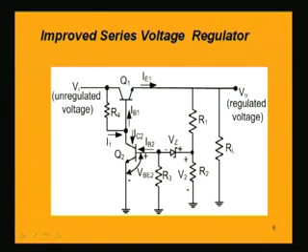So now if we apply again KVL in this loop, starting from here and ending at ground through this resistance R2, what we get? VBE2, that is the base to emitter voltage for the transistor Q2, plus Vz. Mind the polarities, because this is a reverse biased Zener diode. So this point should be negative, this point is positive, and Vz is the drop.